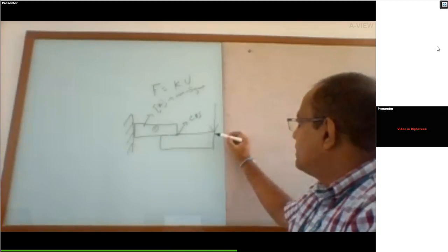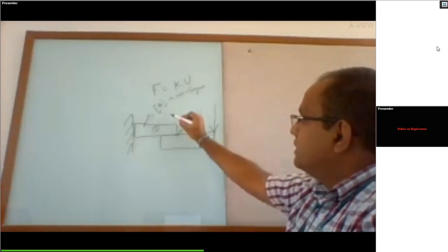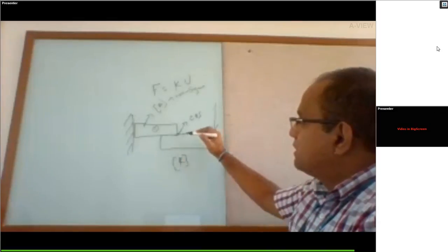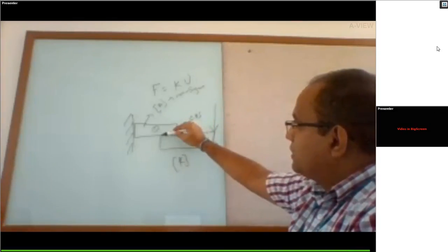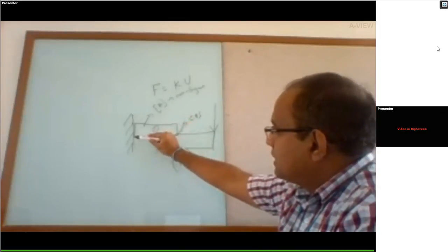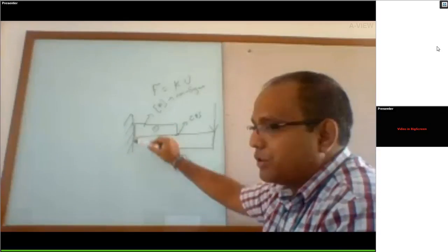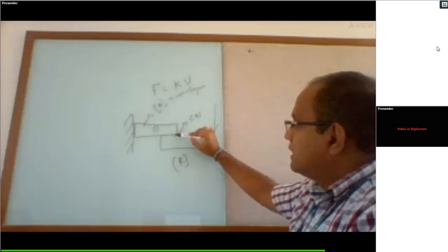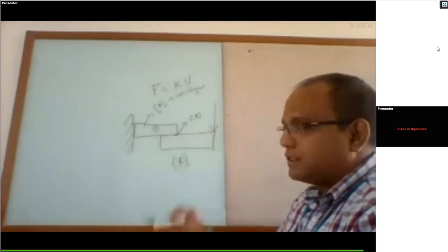But here it is not constrained, so K is singular. This singularity can be avoided if you establish some connectivity from this boundary condition to this component. That relation we can establish by tying this interface with either CEs or CPs.